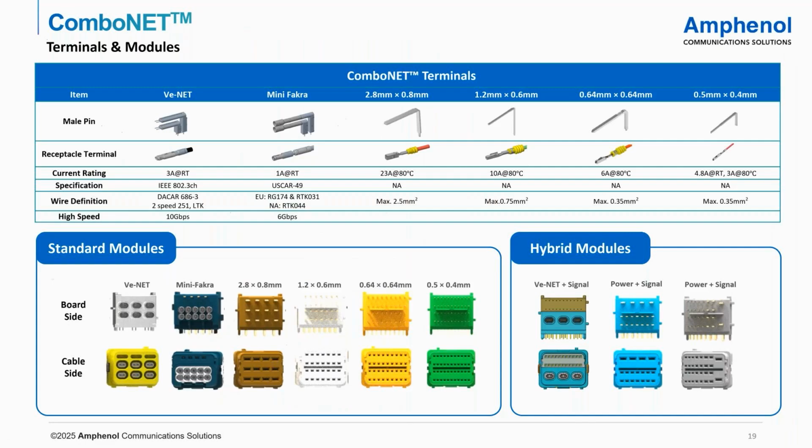When we look at what type of terminals we are using in our modules and what type of modules we have, it's endless. You can do whatever you want. We can put data connectors, power connectors, signal terminals inside our modules. If you have a certain preference for a terminal system, you can let us know, and we build a module according to that terminal system. The only thing which is limiting, but it can still be adapted, is the cable size. If the cable size is too big, the minimum bending radius might cause our connector to get too large, and then we will have to review together with you how we address that issue.